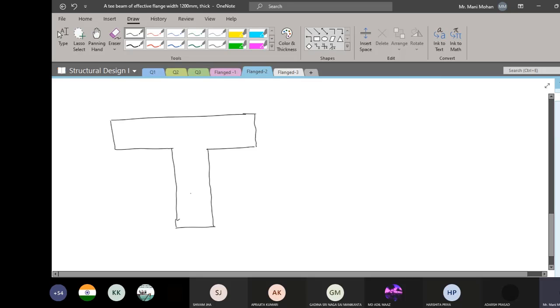So you can guess in that fashion. Maybe your neutral axis is somewhere over here. You need very less area in order to get that 22 kilonewton. Now, in this case, if I draw my stress block diagram, it is possible that the parabolic portion, you can see this is the parabolic portion, a part of the parabolic portion is going to lie in my flange.